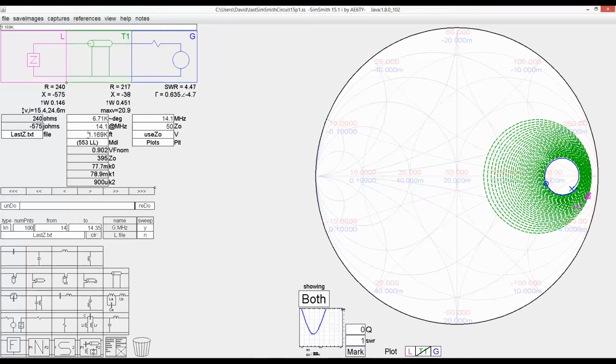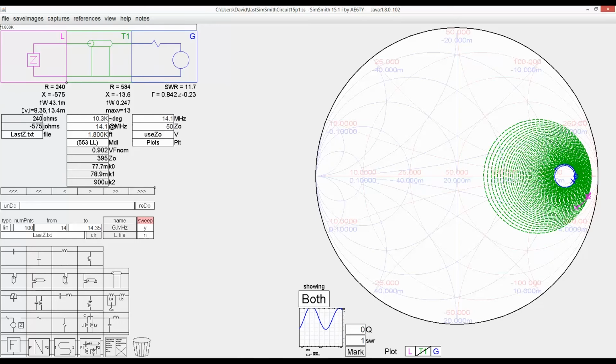The further you go, the more it begins to converge on its characteristic impedance. And if you get, we're at 2,500 feet of transmission line here. If you go far enough, eventually it will just look like a perfect match to its own characteristic impedance, and the rest is just lost. There's hardly anything getting to the antenna. So that's just a little side trip there.